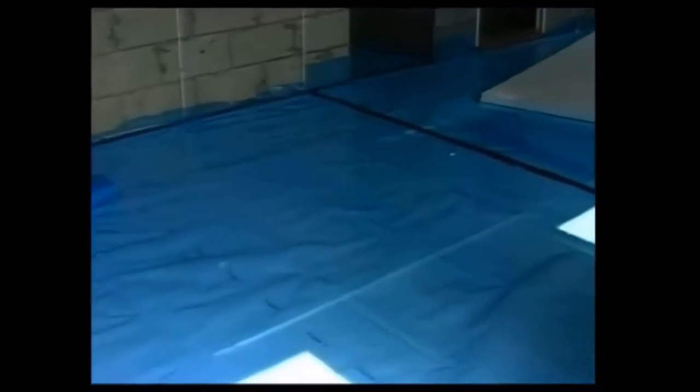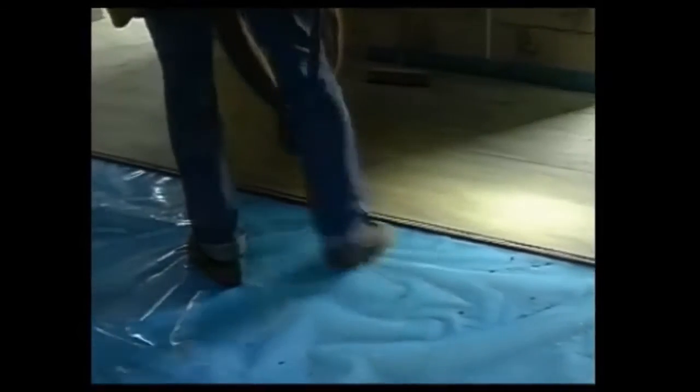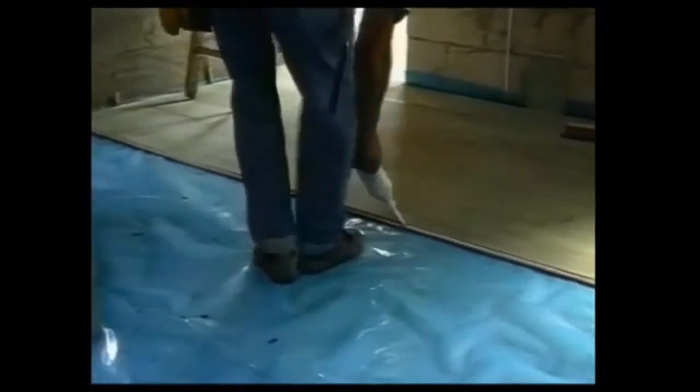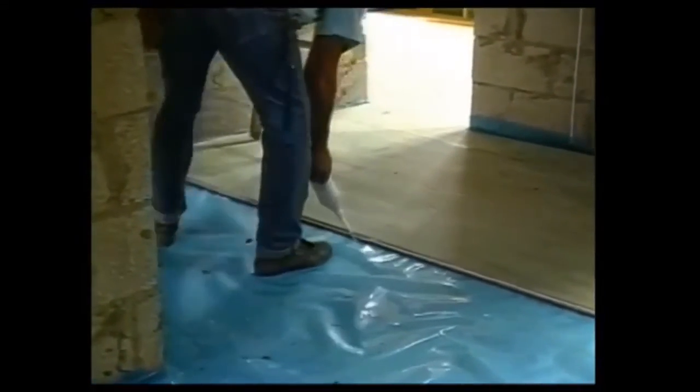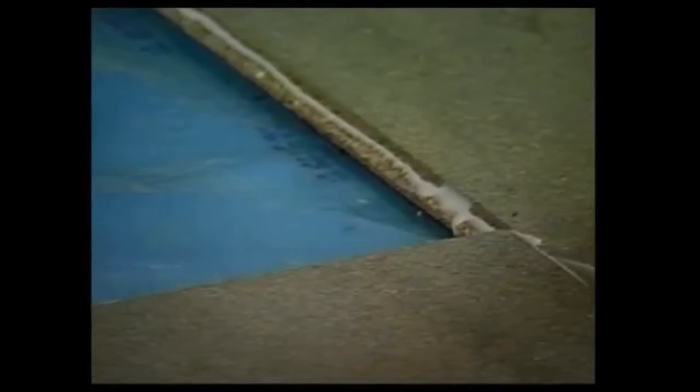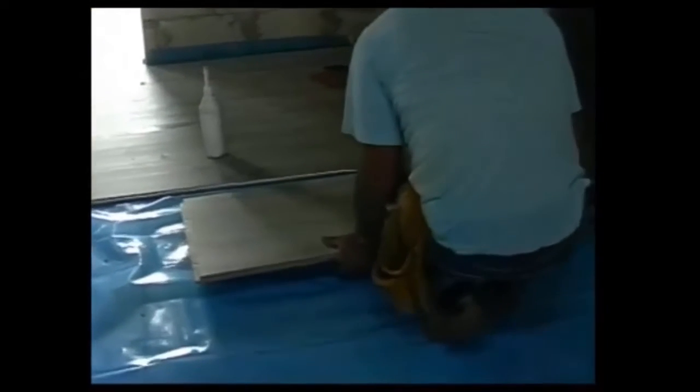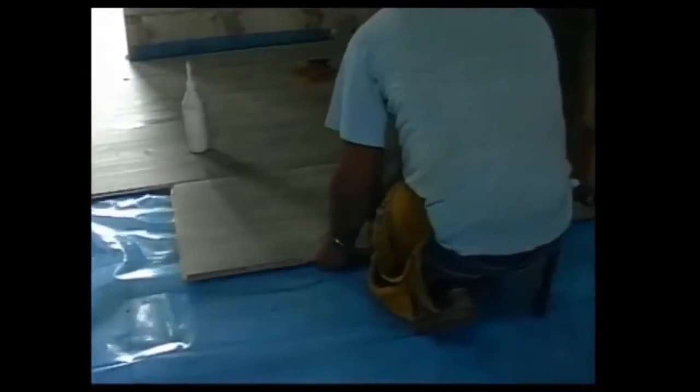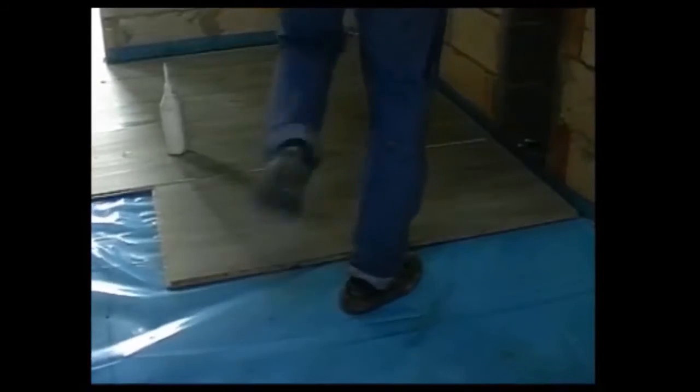The sheets of chipboard have tongued and grooved edges and are simply laid over the polythene. The sheets are not fixed down to the slab, although their edges are glued. In bathrooms and kitchens, where levels of humidity are high, it's wise to use a special grade of moisture-resistant chipboard to maintain durability. Temporary wedges can provide a gap of about 10 millimetres around the perimeter of the boards to allow for future thermal and moisture expansion.